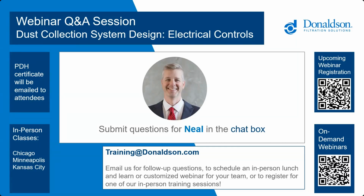Thank you. Next question, do you typically require a particulate analysis to determine the recommended capture velocity and minimum duct velocity for a specific application? That's a great question. To answer your question, if you have it, absolutely. If the customer is willing to go do that, it will help dial it in very well. But I will say at Donaldson, we have the luxury of having so many years of experience. So unless it's something that we haven't dealt with before, we've got a large application database where we can take a look at what the application is and most likely help guide you on that.